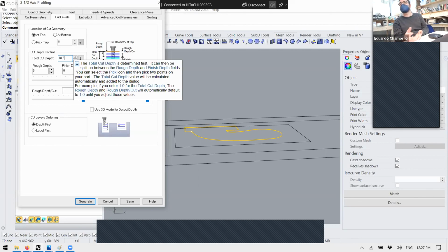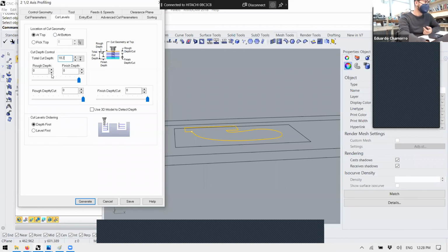Personally, I really love down cutters and straight cutters. They are really easy to use, less sensitive to mistakes. They are not as fast, yes, but they work really well and they give really clean cuts in general. But the downside is the price of the cutters, almost double that of an up cutter in general, and you cannot make faults. That is huge. And say we are engraving, a 2 millimeter touch, it's not going to compress.